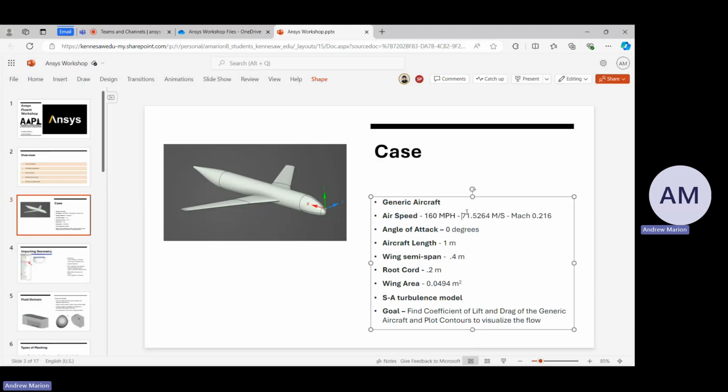And then there's wing twist. Typically you have the root at a high angle and the tip at a low angle. So since the root is at a high angle of attack, it will stall first. You can still control the aircraft because your ailerons are out at the tip. If the tip stalled first, you would lose control of the aircraft and spin, and that's where a lot of the crashes from World War II came from.